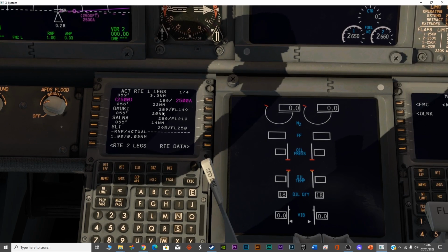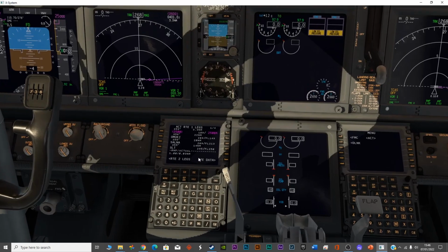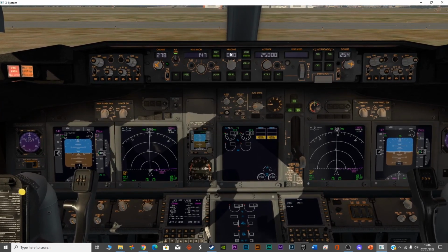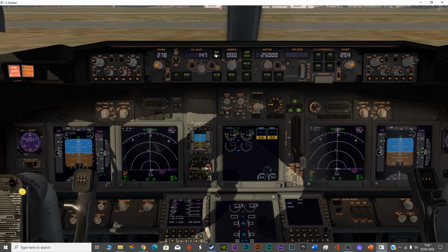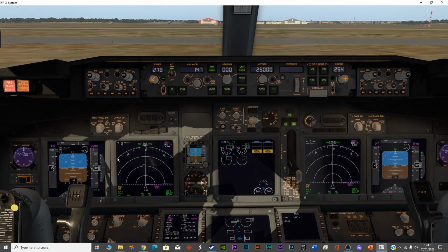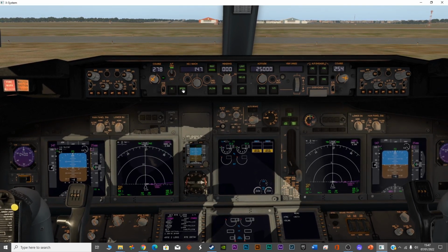Yes, exactly, if I'm not wrong. Yes. Just wanted to clarify, because I was looking, I think maybe the speed was also coming. Anyhow, this is the information. But if you don't turn on the LNAV and the VNAV option after the takeoff, you can also select the heading selector, and the plane will start to fly in the heading of 360 degrees, like in a straight path. And if you engage the speed, then you can adjust the speed over here.